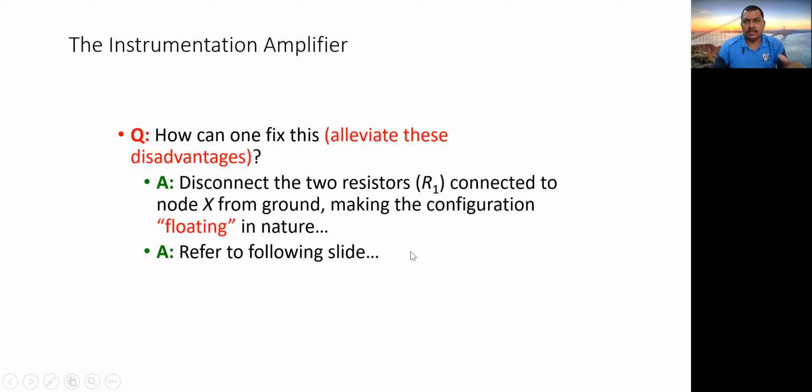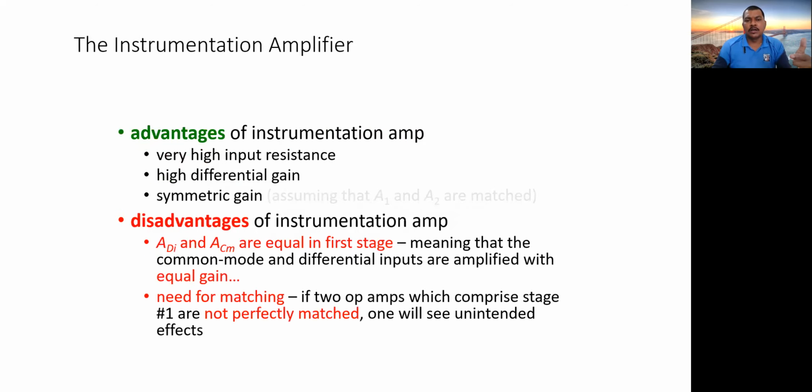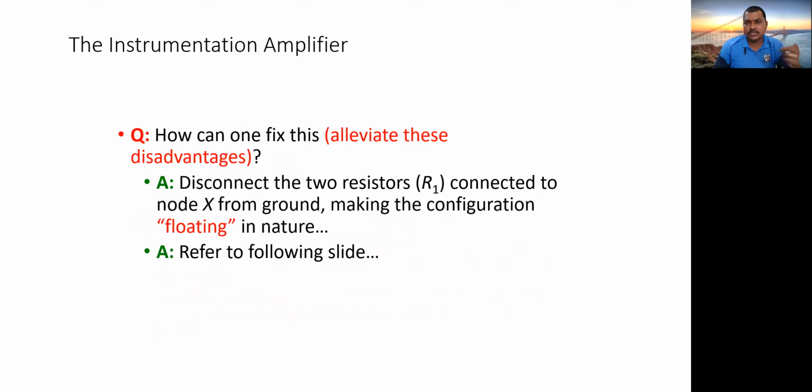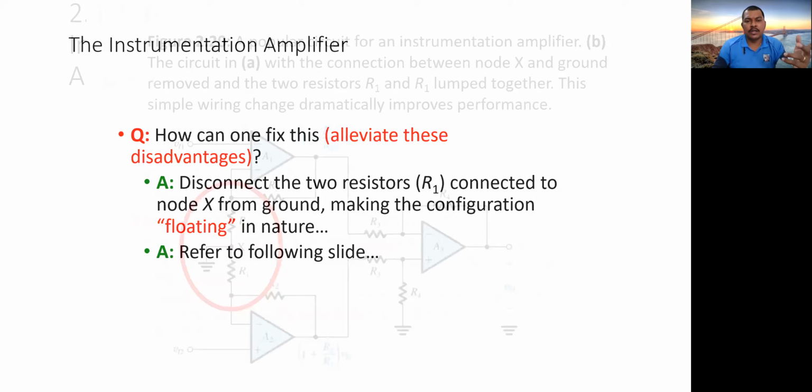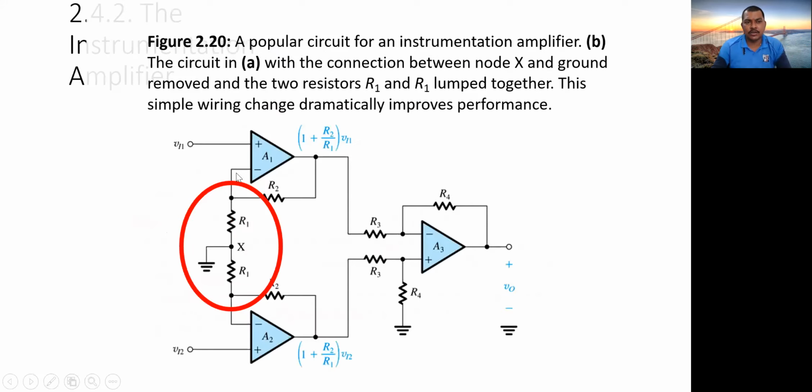So again, I'm going in depth, though we are not expected to write this much. We are expected to write that instrumentation circuit only, but this can also be achieved by just replacing that R1 and R2. So remember this. This was the circuit of the instrumentation amplifier. This is only what is required in your syllabus.